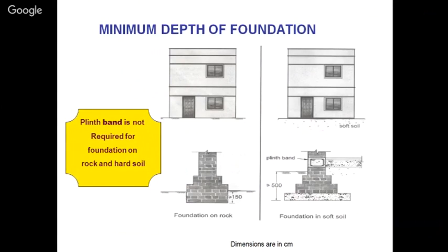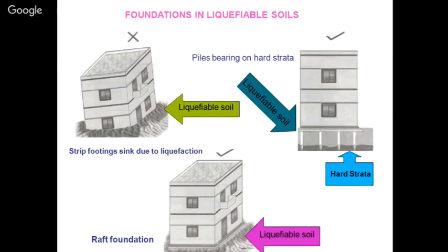Foundation in soft soil, foundation on rock. It is not required on rock, but as compared to other than rock, you are supposed to provide the plinth band. Foundation in liquefiable soils: strip footings sink due to liquefaction. So you are supposed to consider all these things.